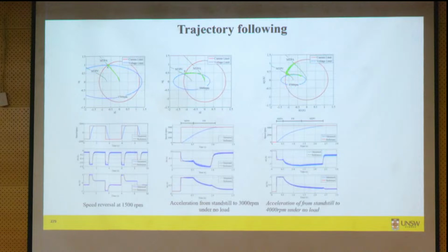You can see here an example done using some of our IPM motors that has MTPP. You can see how the trajectory is followed during the experiment. If you calculate the ID current correctly, that green graph is showing a real-time trajectory following for a prototype motor. And you can also see how the ID current is changing. So in MTPA, ID current was here. In flux weakening, ID current was dropping. And then MTPP,